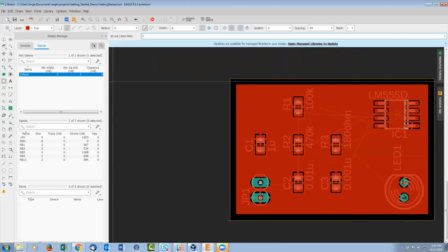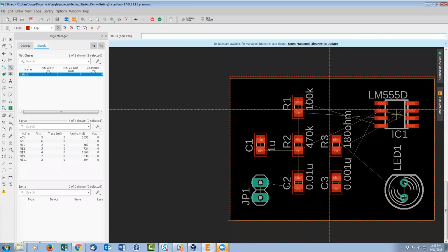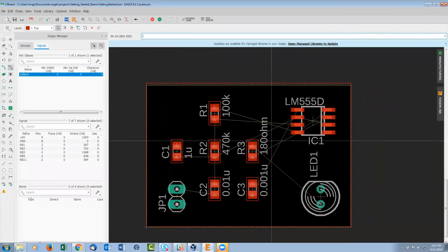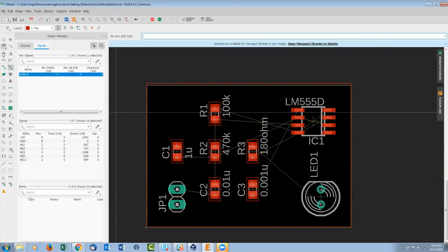Okay, and we can use the rip command to turn off the polygon, you'll see here, rip up all polygons. And we'll get back to this view. This view is preferred when routing, because that way you don't have all that color cluttering your routing area. Now, how do we route? Routing is done using the route command over here. And you'll see there's lots of options.